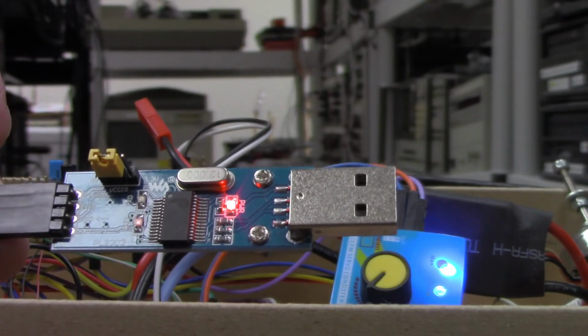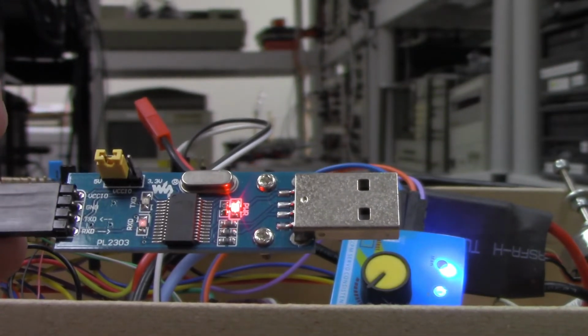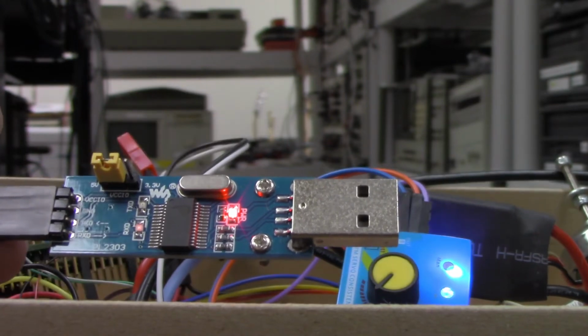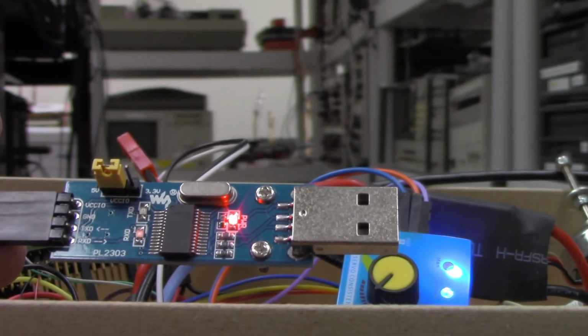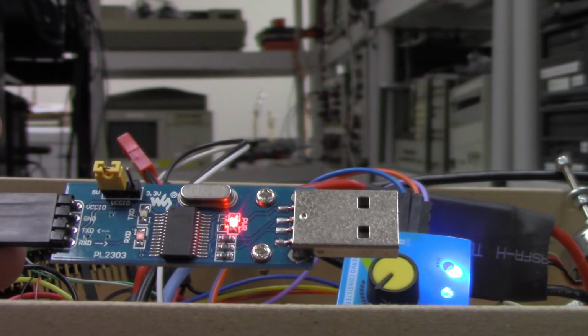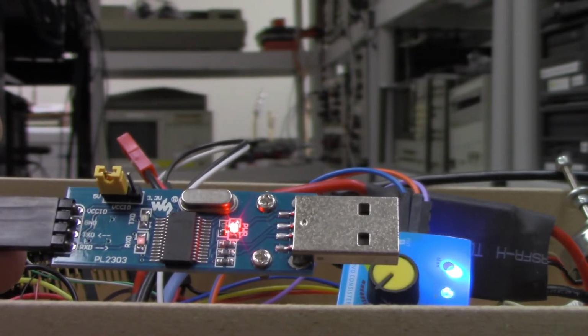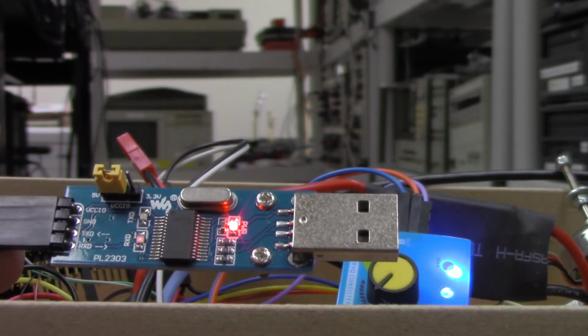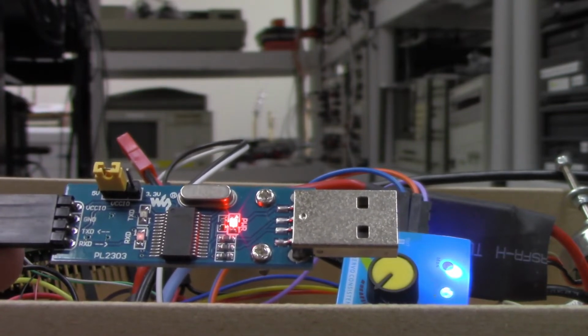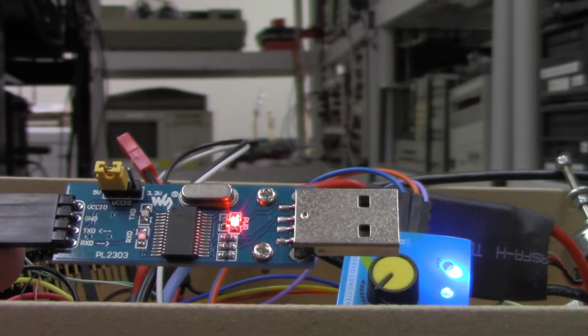I believe the last module I have here is the PL2303, and that takes the UART type signals, like a serial output, and sends it to USB. So I can read it using Tera Term. I use this for instrumentation purposes to help debug this real-time system.